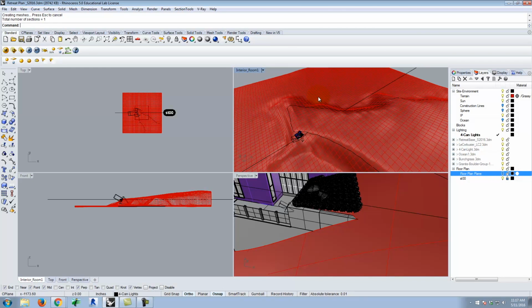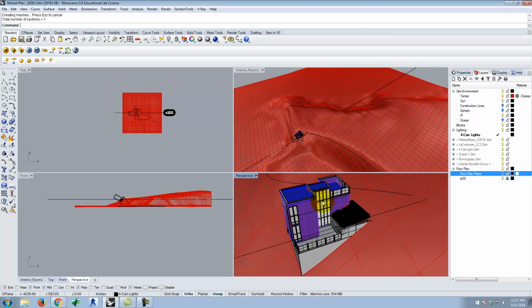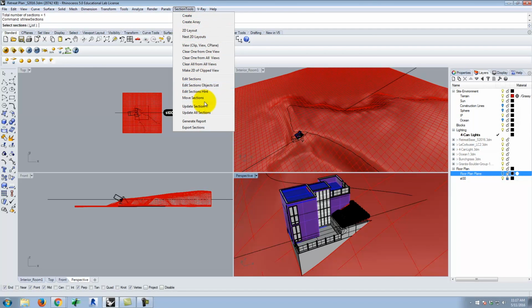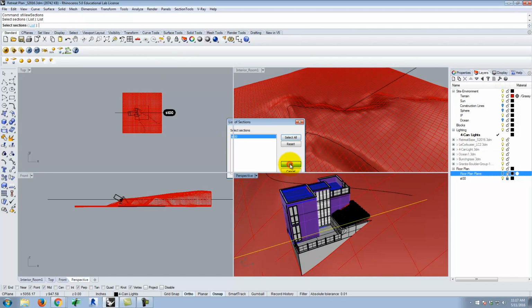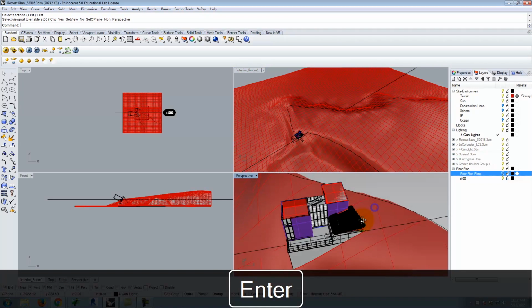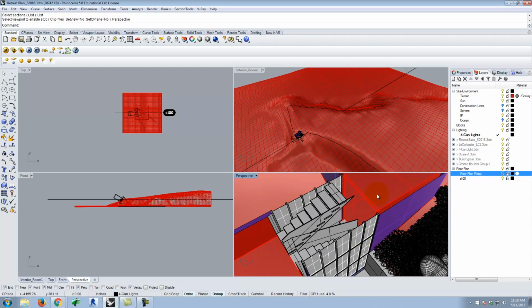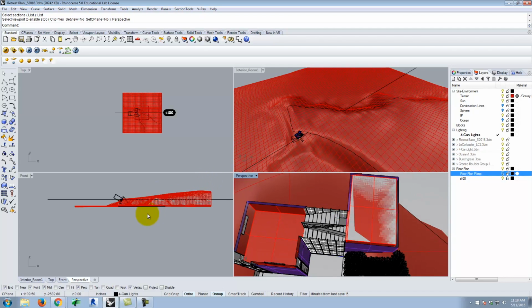And in, say, this, let me go into just the perspective view here. Okay? In the perspective view, I can type ST-view or go up to my section tools and then view sections right there. And I'm going to list it, and I'm going to choose ST00. And what view do I want to see this in? Right now we'll look at it in the perspective view. So I'll type perspective. And now we can see that I've cut through my building there. Looks like I actually missed and didn't quite cut through the top roof of that building. So I have a ceiling. So I'm going to do this one more time, and I'm going to lower it so that I can actually cut through that because I want to see into my building.